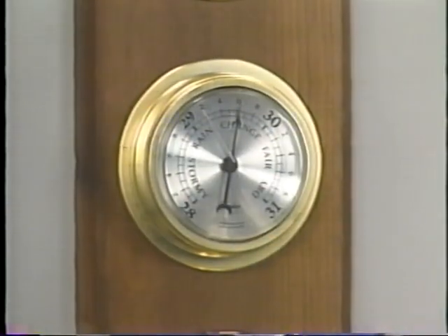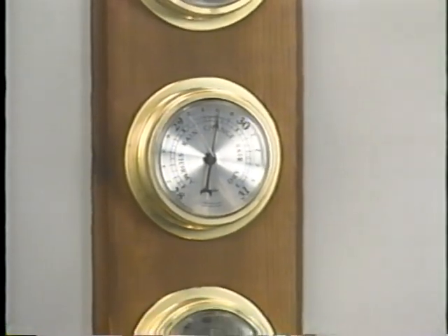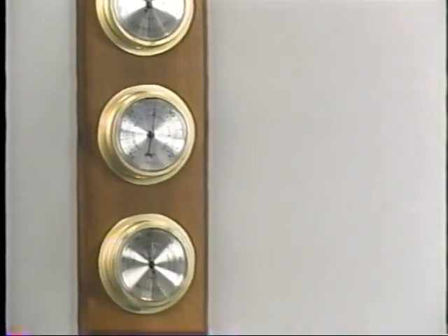The barometric pressure reading is just as important as the manifold absolute pressure readings are. The PCM uses the baro reading to calibrate the values it sees when the engine is running. So if the barometric reading is inaccurate, it throws off the PCM's fuel delivery and ignition timing calculations. The effects can be severe enough to cause an engine performance problem, yet this condition would not cause the PCM to set a trouble code.